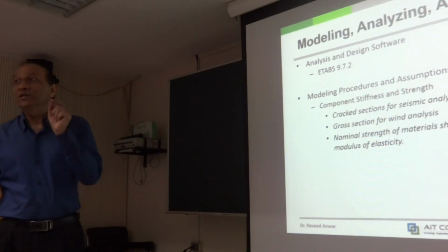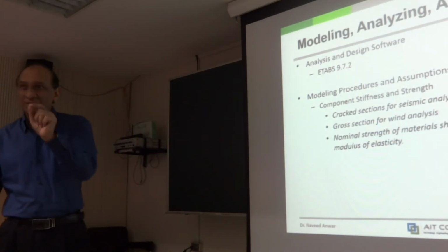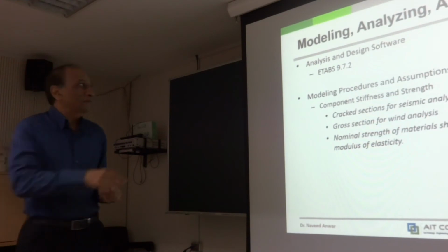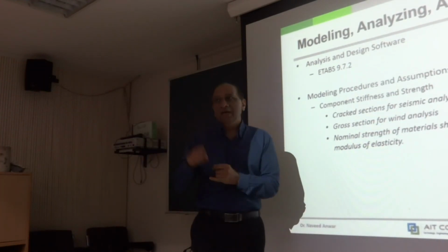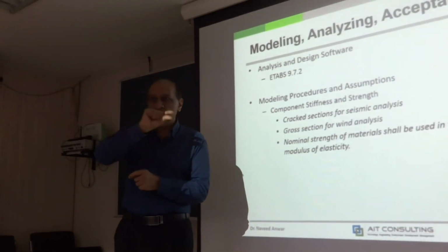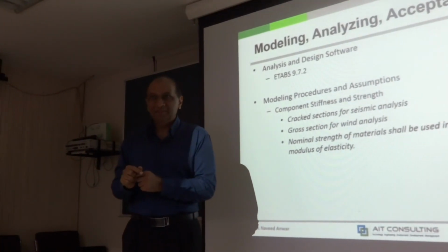But this is something that you need to write in your design criteria. So another person who's maybe more knowledgeable or less knowledgeable than you should know that this is the assumption that you use. So normally we write down, I'm going to use a cracking factor for column so much, beam so much, for wind so much, earthquake so much, right?